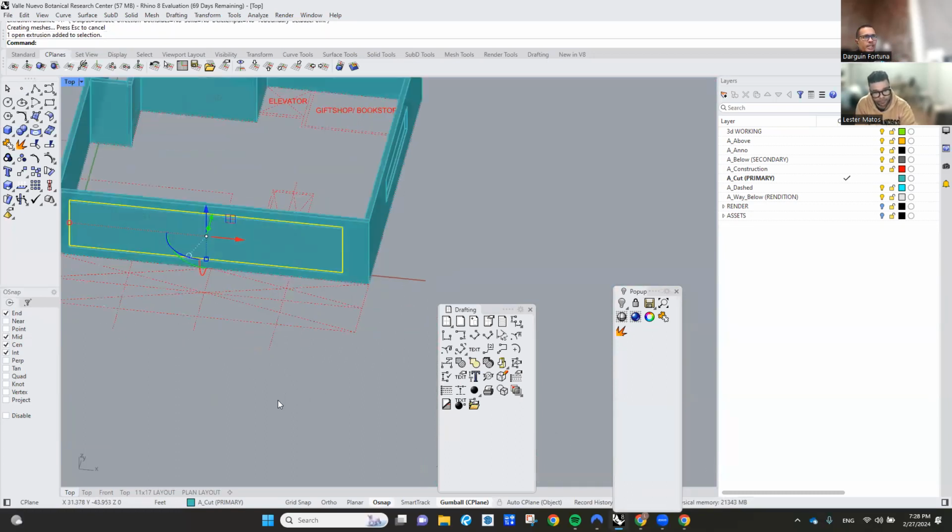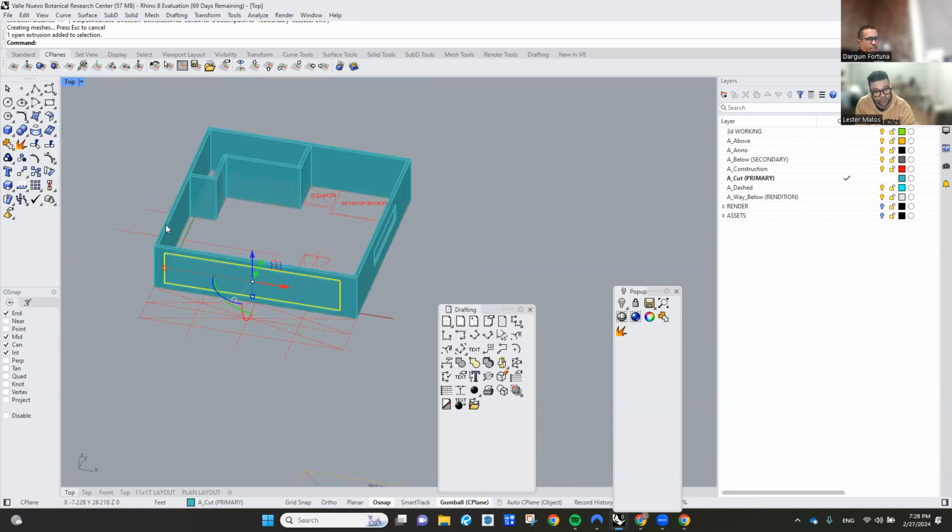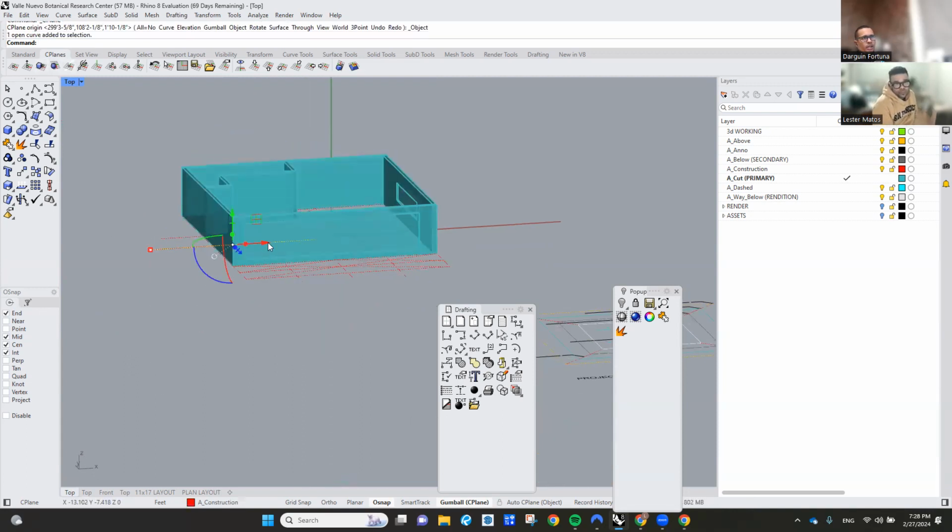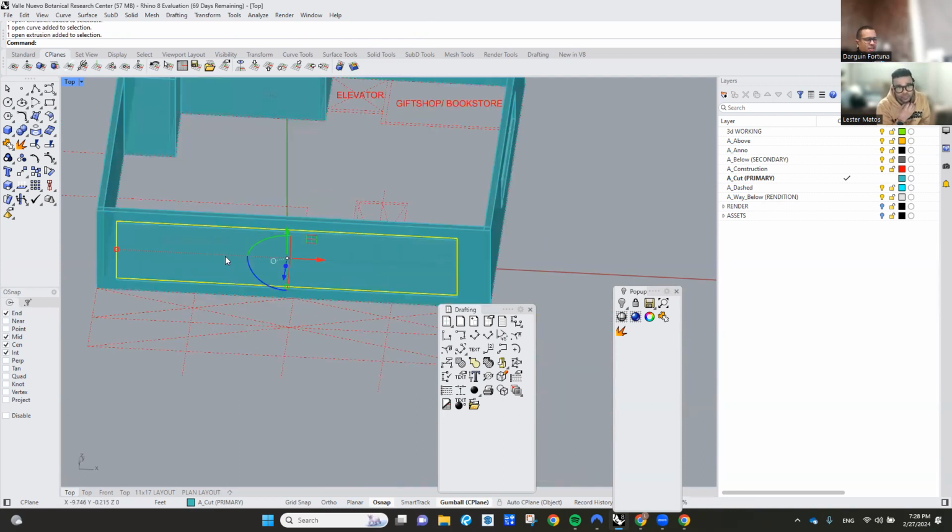So in this case, and this is all being recorded, so you can watch it anytime, so don't worry. I'm gonna pick that face as my C-plane, boom. And then I'm gonna go in here and say, I don't even have to have it selected, I think, but I'm going to select it anyways. Select it, and I'm gonna say contour.